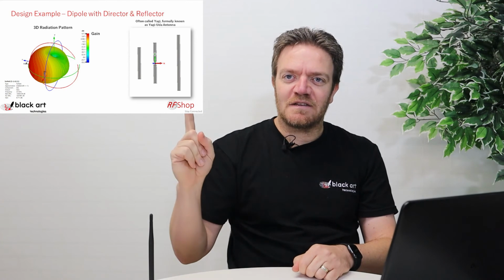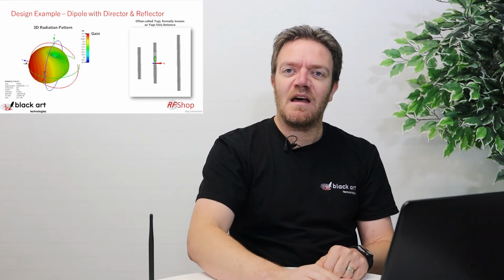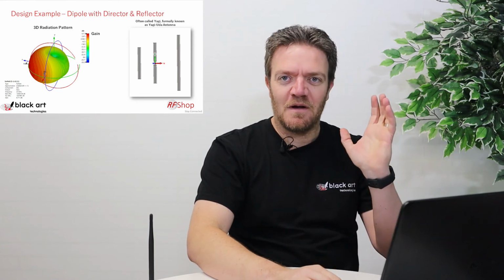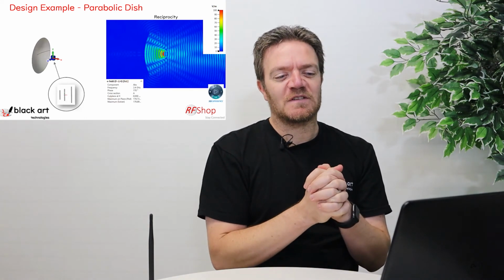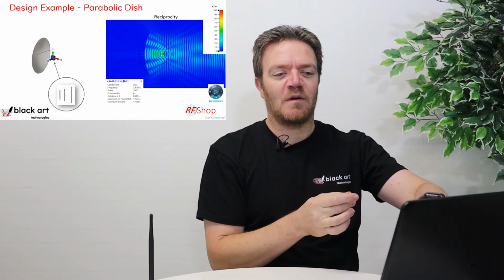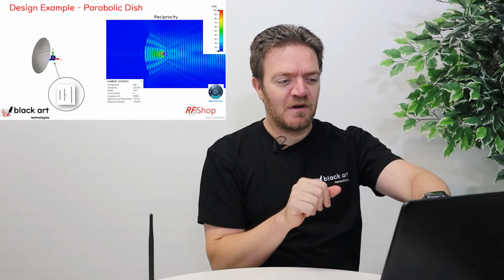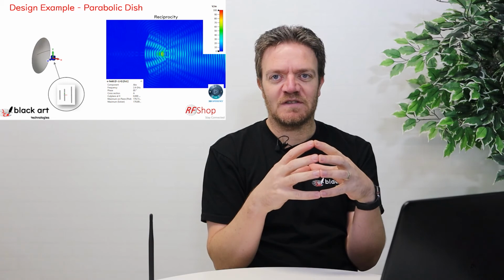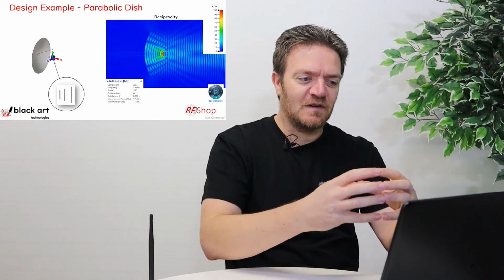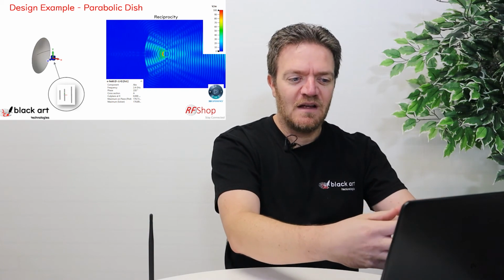I added the reflector, I added the director to the antenna, so it became much more directional. Now, I put that thing in front of a parabolic dish. That's what starts to happen. So first, you can see in my picture, there's the antenna that I created by those 3 building blocks. I put it in that area there. So you can see there's a small blue cube. So that's just the numerical technique that I use in CST, so I can put it in there. So that's the space where I put it. That's the focal point for this dish that I created.